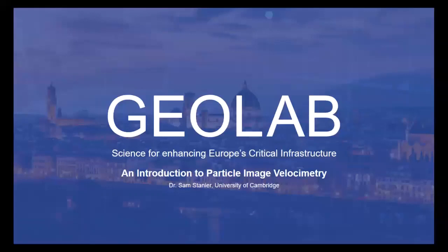In terms of centrifuge model tests, I can envisage that people might want to use multiple cameras to image the surface of a sample. You might want to look at a settlement trough above a tunnel or something like that. We've been playing around with that in Cambridge a little bit, but we've not really seen any meaningful output from that. I think it's quite challenging to identify where the coincident points are in both the cameras' fields of view. And we've done quite a lot of work where you take a sensor location in one image, you project its position onto your model in order to then infer where that point ought to be in subsequent other camera fields of view. And then you can use PIV to refine the measurement. But I've not seen much output from that yet. That's more Stuart Haig's work than mine.